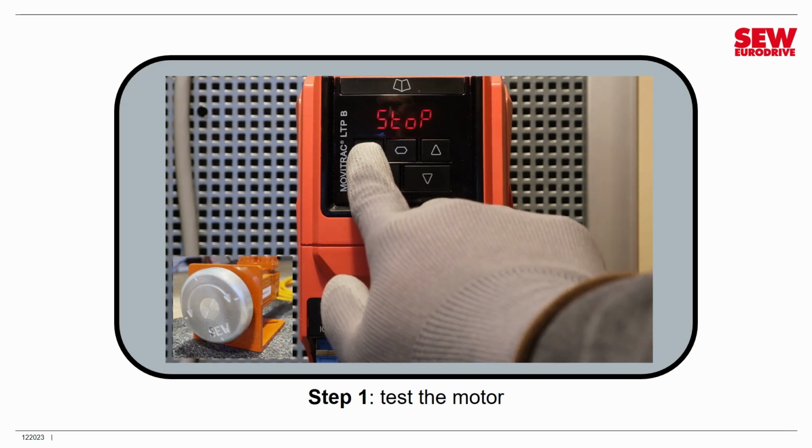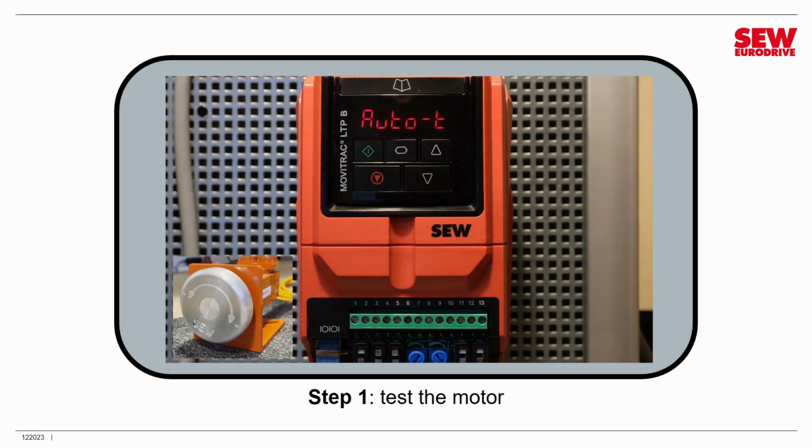And I'm going to press start, and that's going to trigger an auto-tuning cycle, and you can see it just did. It's tuning. You saw the motor twitch a little bit. It's also making some funny noises. This will take a few more seconds. Eventually, though, it'll display stop, as it does here, and now it's ready to run.